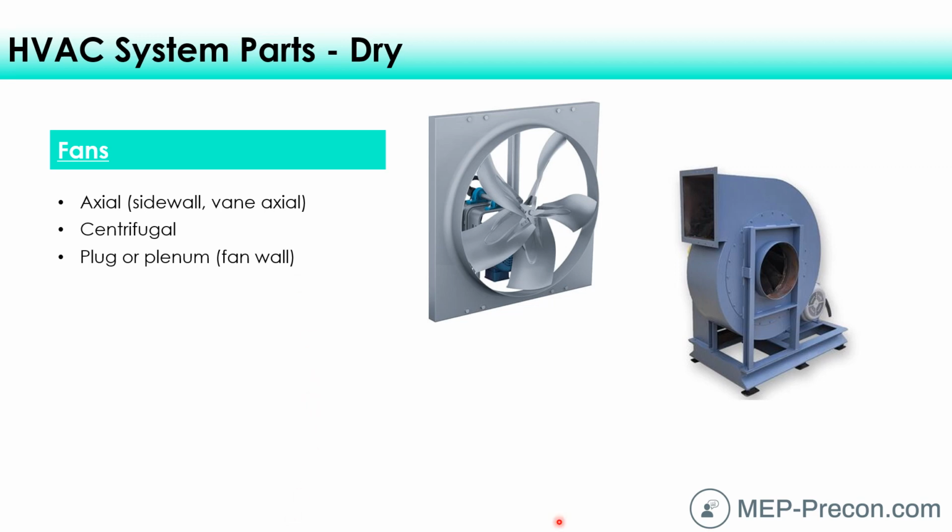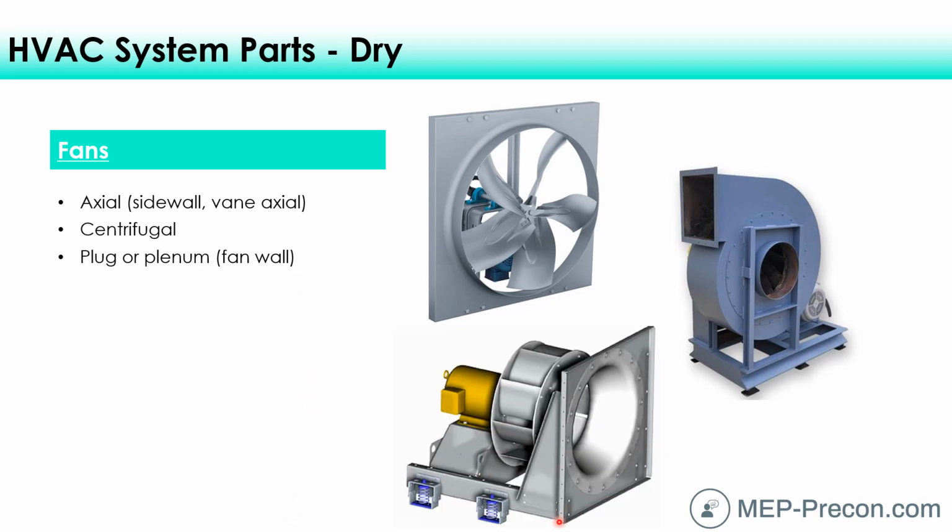And then also there are plug or plenum fans, which are essentially a centrifugal fan with the housing removed. These you'd find inside of air handlers, or it could be part of a fan wall. You can see how these could get mounted on top of each other or on the side of each other. Fan walls have developed a lot of popularity recently because they don't take up a lot of space,